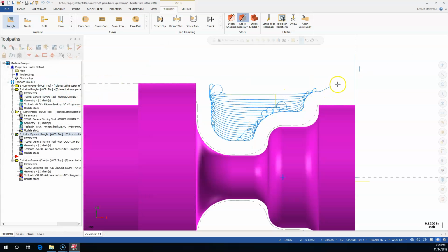That's going to be my dynamic, and it's out here cutting quite a bit of air to bring it into those sizes before it comes in, and then we're still going to need to bring this back and make a finish pass. So I don't know that this is going to be any more efficient. It's a nice looking tool path, but if I could finish down this wall to the tangency, I could probably get this to clean up a little bit further, at least making the first cuts at this outer diameter. So that's what I'm going to need to experiment a little bit more with.